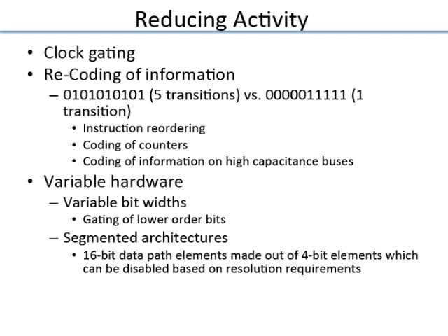If you know that that particular piece of logic is not required, that whole group, you can turn off the clock. You turn off the clock by just putting an AND gate, and you have a gated clock coming out. But make sure that the signal for the AND gate is controlled, and the transitions on that signal happen at the right time, so that you don't have false edges in the gated clock signal at the wrong time. So that is clock gating.